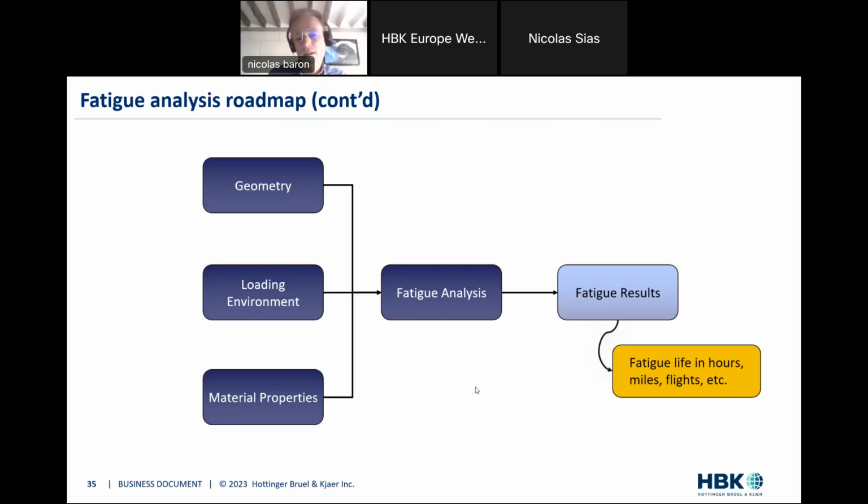So it might make sense to express this number of repetitions in terms of hours, but of course, it might be more meaningful for you, maybe if you're working in the car industry, to express that in the number of miles or kilometers that your car will be able to withstand before breaking. Or if you are working in the aerospace industry, the number of flights, taking off, flying, landing, the number of flights allowed for the fuselage before showing some fatigue weaknesses. So fatigue will be expressed in these terms: hours, miles, flights, repetitions of the input loading. That's really how you will express fatigue results.